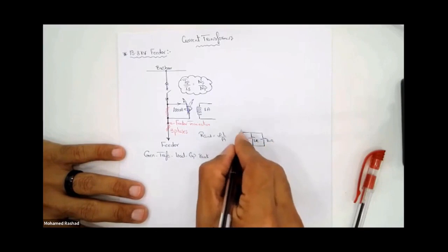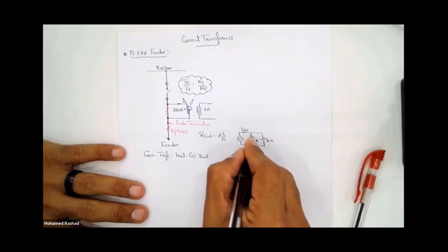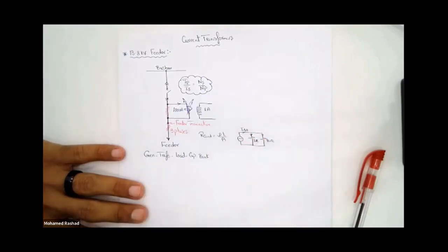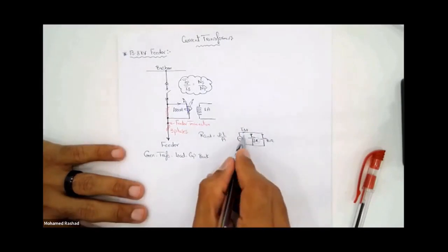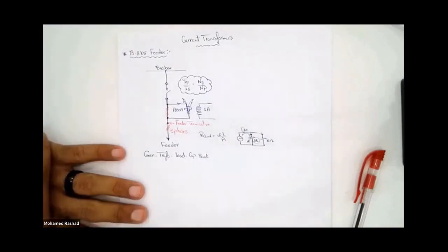in this case, the total current, a large portion of it, will flow through the 1 ohm resistor, and a smaller portion will flow through the 10 ohm resistor. It will act like a current divider based on the resistance value, meaning the lower the resistance, the more it will draw the larger share of the current.